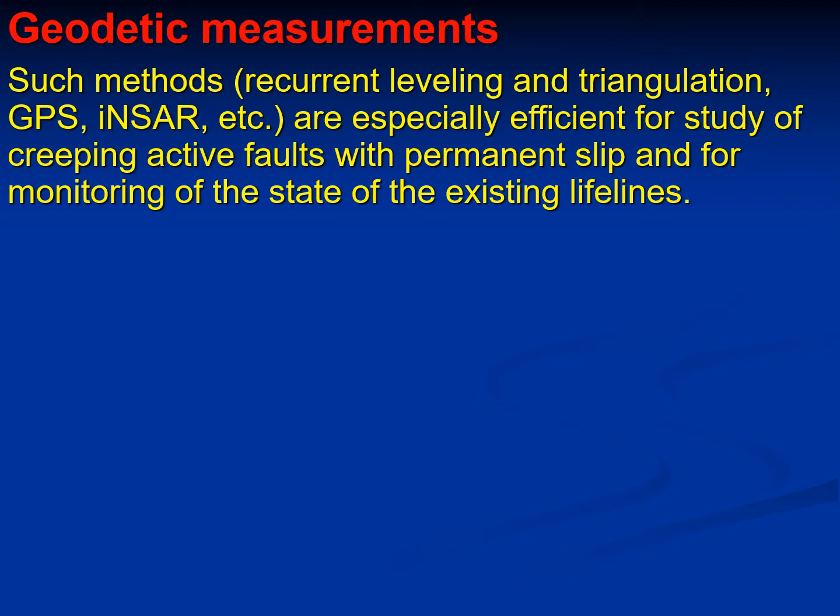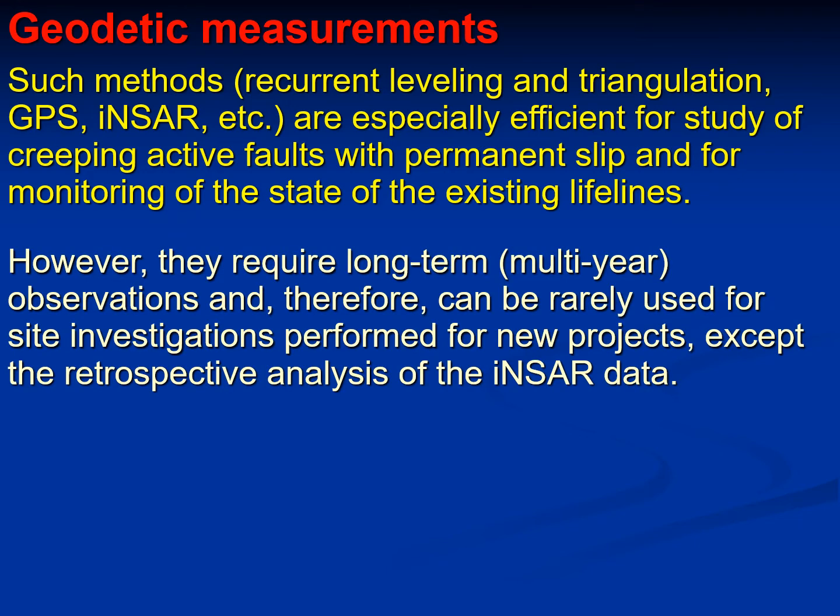Geodetic measurements: I will not stop on them in detail. I just want to mention that such methods, recurrent leveling and triangulation, GPS measurements, InSAR and so on, are especially efficient for the study of creeping active faults with permanent slip and for monitoring the state of existing lifelines that cross active faults.